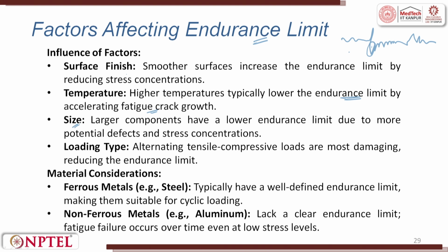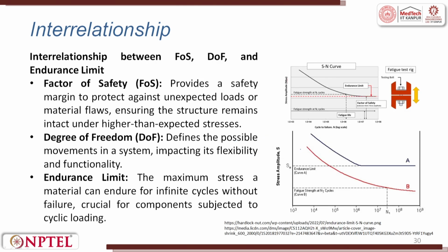Size: large components have a lower endurance limit, because there is a possibility of more defects, and achieving surface roughness is also more difficult. So, large components have a lower endurance limit due to more potential defects and stress concentrations. The loading type: alternate tensile and compressive loading is most damaging, reducing the endurance limit. For material consideration, you can use ferrous or non-ferrous material. When you talk about ferrous, we talk about steel. In non-ferrous, aluminum and titanium are always used.